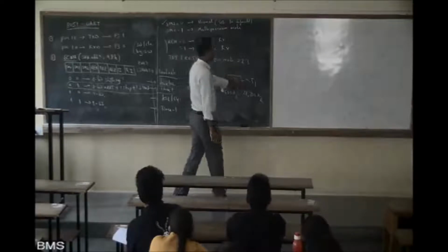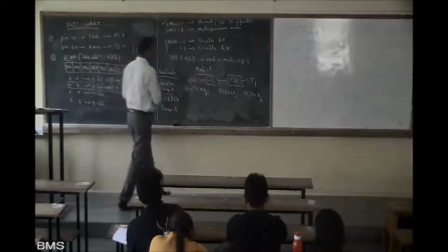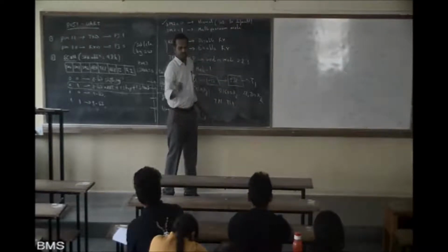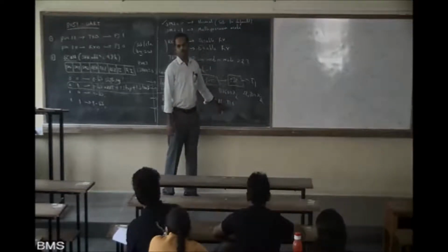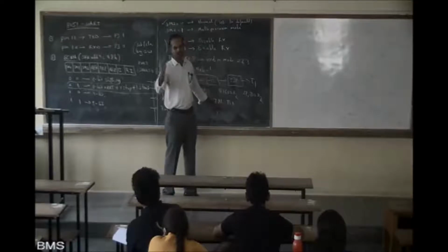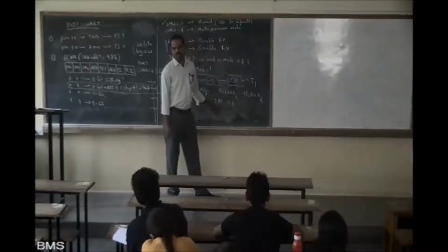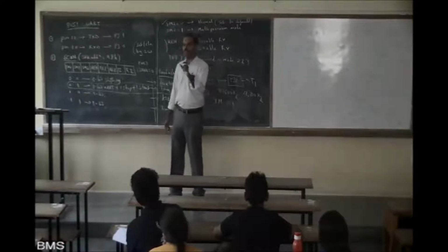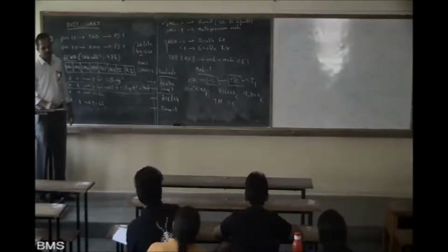Timer 1 has TH1 and TL1. If I operate this continuously, we will operate it in mode 2, that is auto reload mode, not the 16-bit mode 1. In mode 2, auto reload mode, we give a value to only TH1. Now if I want a baud rate of 9600, what should be the value for TH1?